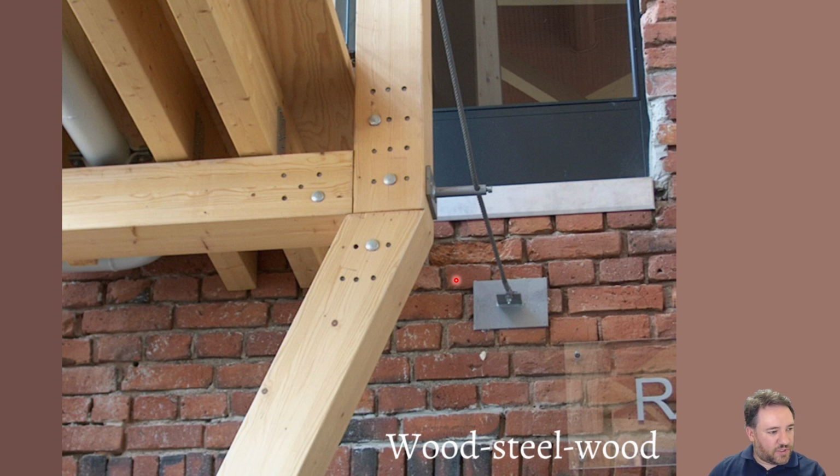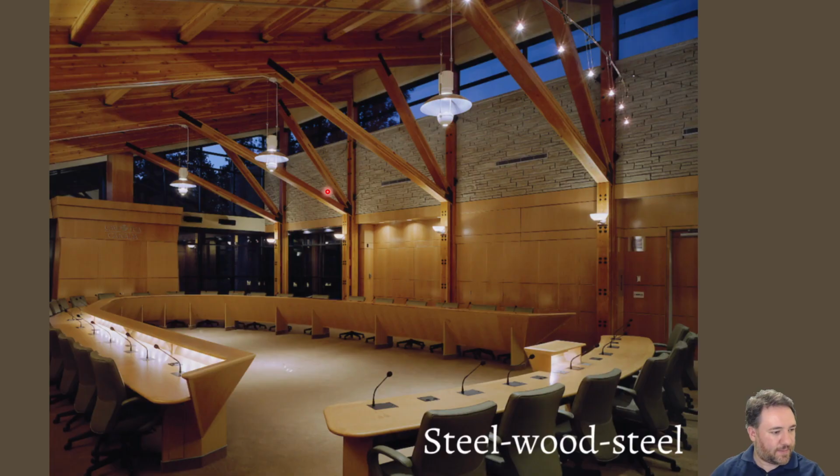Okay, this is another wood, steel, wood. Here you don't see any steel at all, but you can tell there must be something in between these because these wood members are not slotted into each other. There's no mortise tenon joint or anything like that. So there's a hidden steel plate in here, and there's a steel plate that is in all 3 of these at once, and then the bolts hold the steel plate in place.